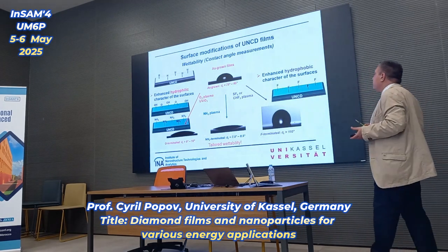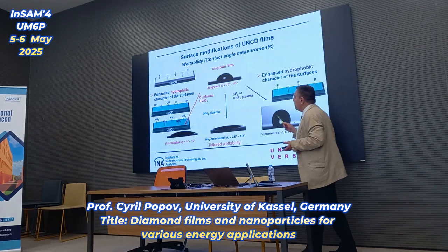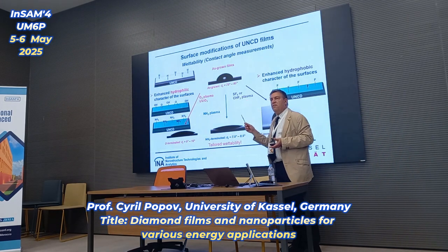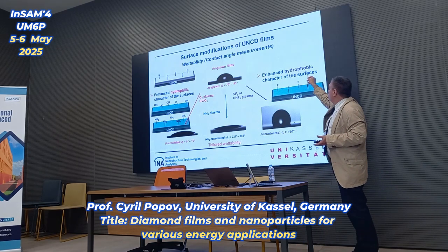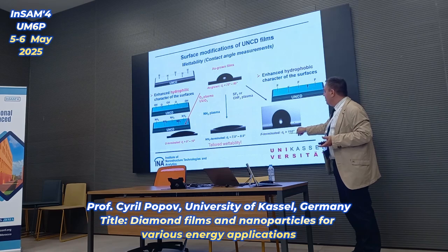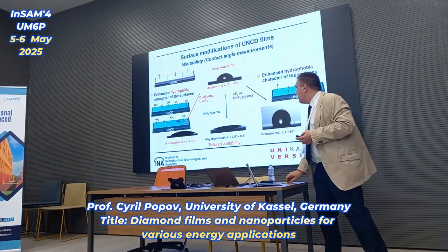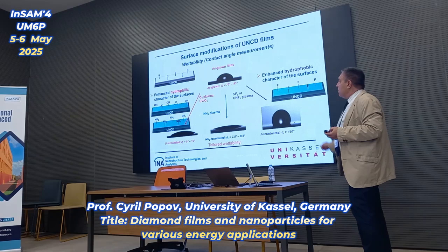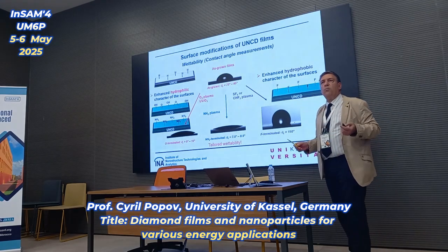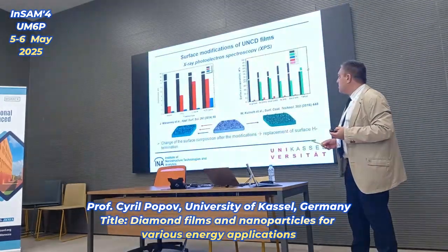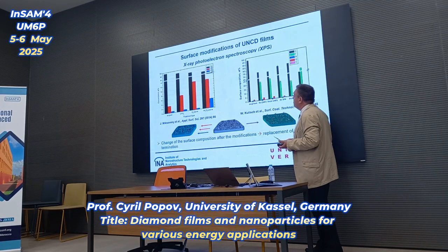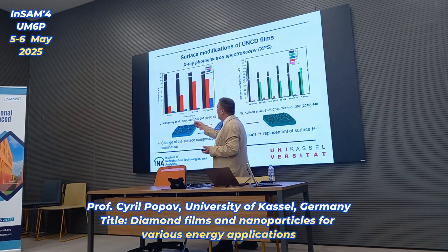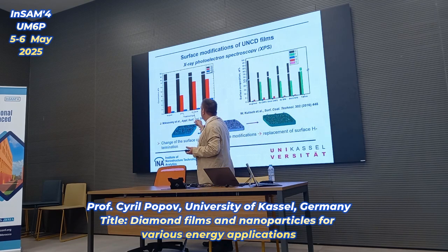In the opposite case, if we use fluorine containing plasma, for example, sulfur hexafluoride, trifluoromethane, we obtain strongly hydrophobic character, so with contact angles higher than 110 degrees. So these modifications are accompanied by exchange of the surface termination, and this is proven by X-ray photoelectron spectroscopy, showing, for example, by UV ozone the increase of oxygen, even higher by oxygen plasma.